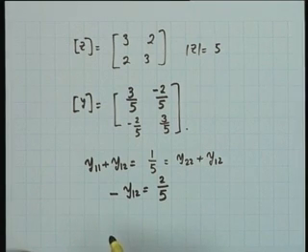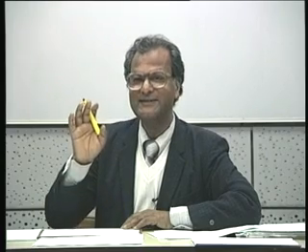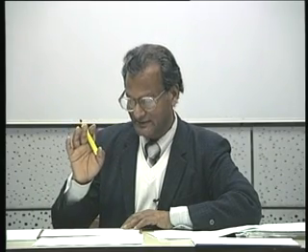Directly we can add the Y parameters of the second circuit. That will be 1 by 2, minus 1 by 2, minus 1 by 2, 1 by 2. We don't want to do that. You'll see that things are simpler than that. Our problem is not to find the Y parameters. Our problem is to find the equivalent network. So what we'll do is we shall draw the equivalent of this.